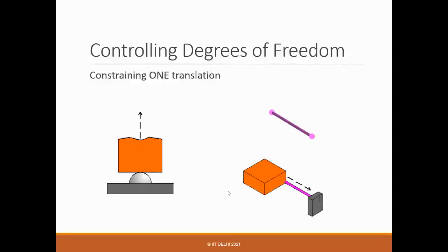So it's just a truss member, and because it can rotate at the joints, what you realize is that the connecting body, which is orange here, with respect to the frame, is constrained along the longitudinal direction, along the direction of the truss member. So if you have the joints, then you can define the constraint line.